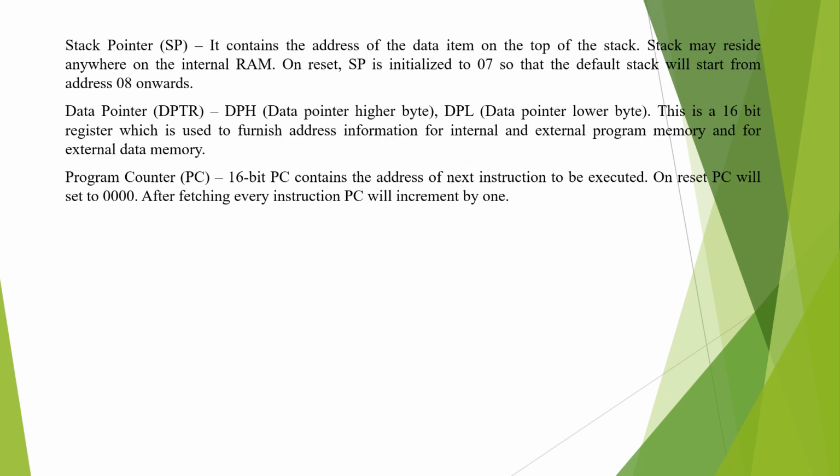There are three important registers also available for 8051. The function of the stack pointer and program counter is the same as 8085 or any other kind of register, but in this case the stack pointer contains the address of the data item on the top of the stack. The stack may reside anywhere in the internal RAM.